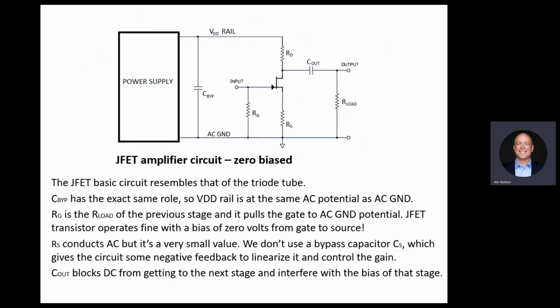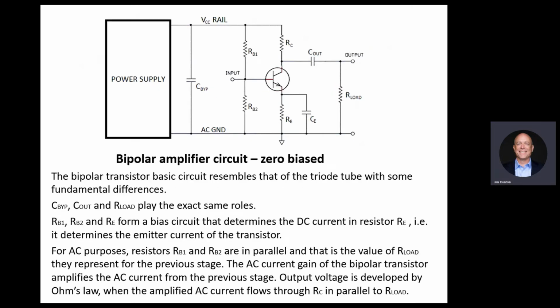With bipolar, you're dealing with low resistors. There's real current flowing here. So you're loading the previous stage, and those resistors are not negligible. They have noise and so on. So there's a reason why people use less and less bipolar in current preamp and phono stages.